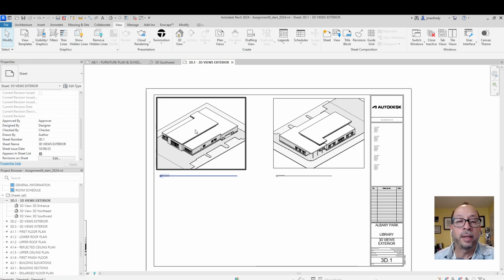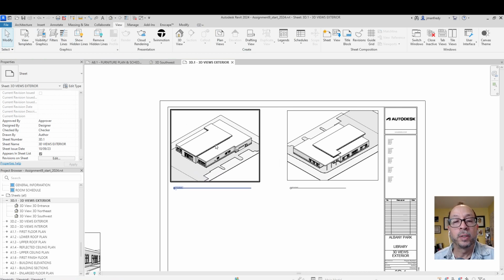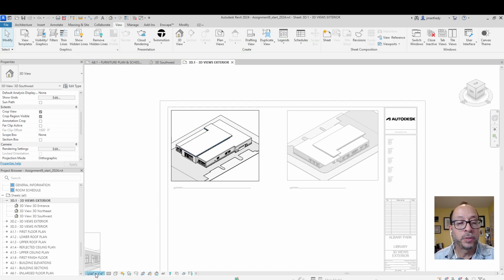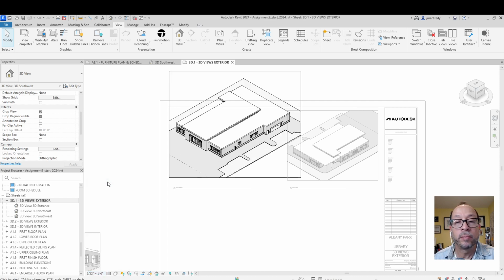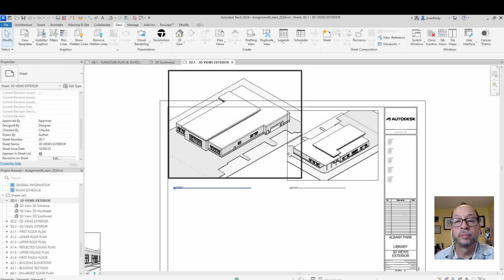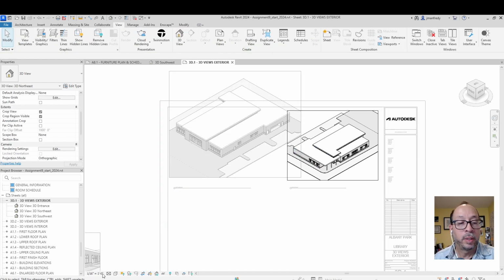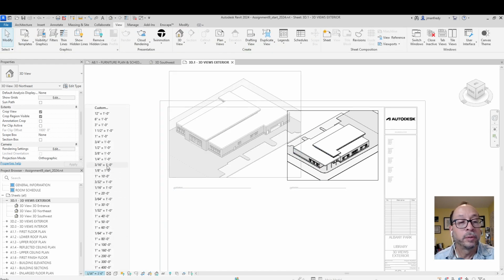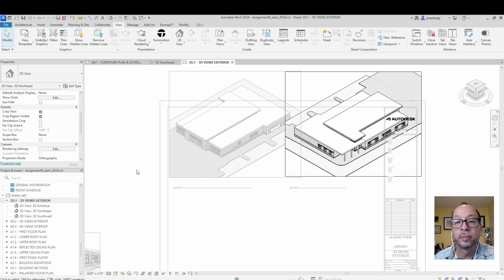So to make isometric drawings bigger, you click on them and you change the scale here. I'm not sure if this will work, but if I'm at 1/16 of an inch, I'm basically here. I can make it slightly bigger here. If I click on this one, I can make it slightly bigger here. 1/16 was here. I'll make it 3/32. See how that looks.